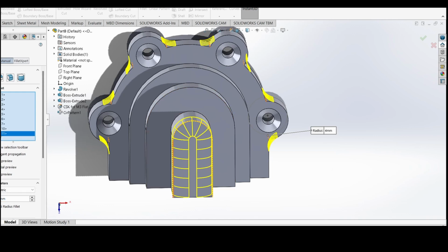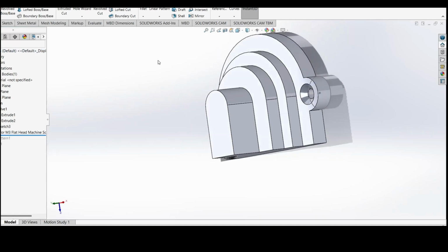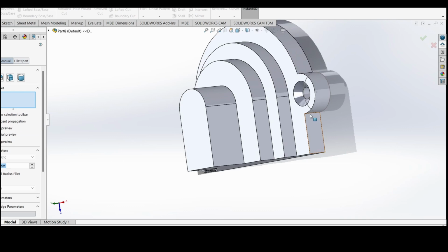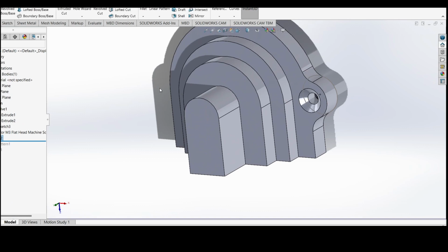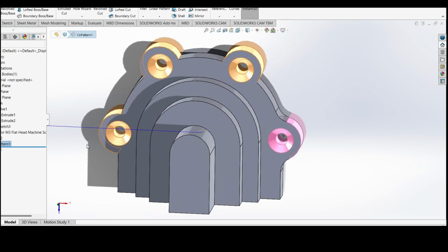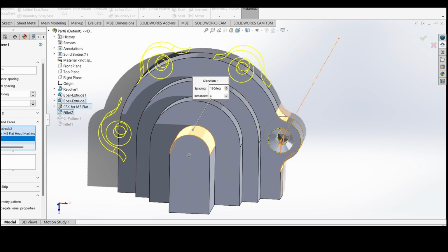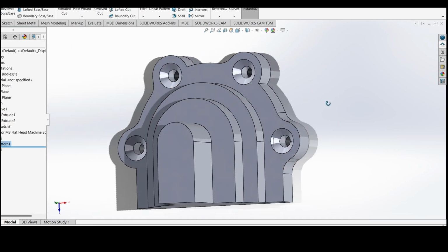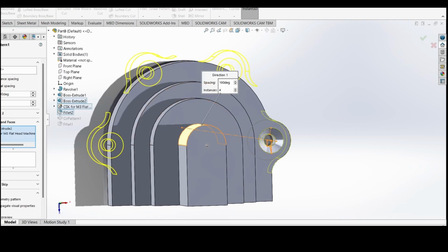You might have thought, wouldn't it be better to put the fillets in here and then linear pattern the fillets, or sorry, circular pattern the fillets. But circular and these feature patterns tend to have a hard time. Let's see if it works. Fillet. I did say make these 2 fillets, didn't I? But look what's happening. It's only doing it on the one side for some reason.